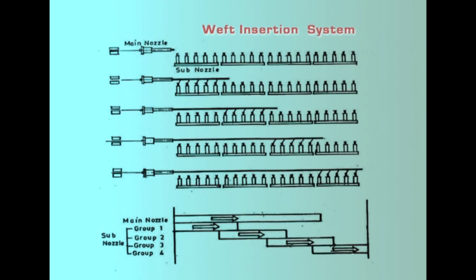As in all shuttleless looms, it plays a very important role, as every pick is inserted and then cut. It is important to cut the pick at the other end of the fabric, otherwise the yarn will come back. The pick that has been inserted will be drawn back continuously, hence the yarn there needs to be cut.